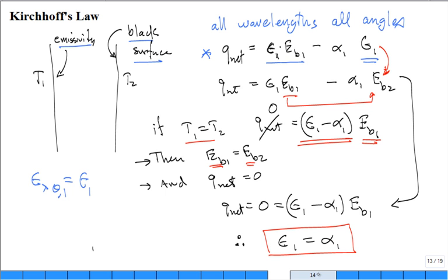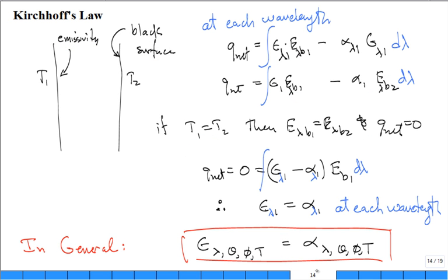But first, let's expand it by relaxing and saying at each wavelength, do the same thing now. See, we started, then we did two blacks, now we do one gray with the emissivity and the other surface black. Here you have it where I'm interested in the surface 1 has emissivity, but it's the spectral emissivity of surface 1.